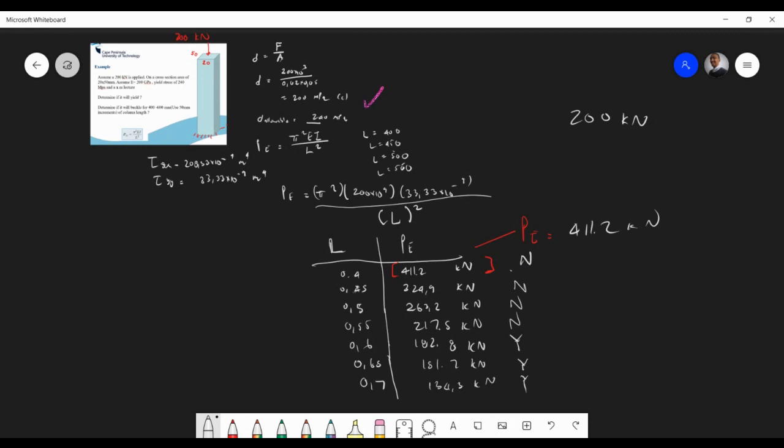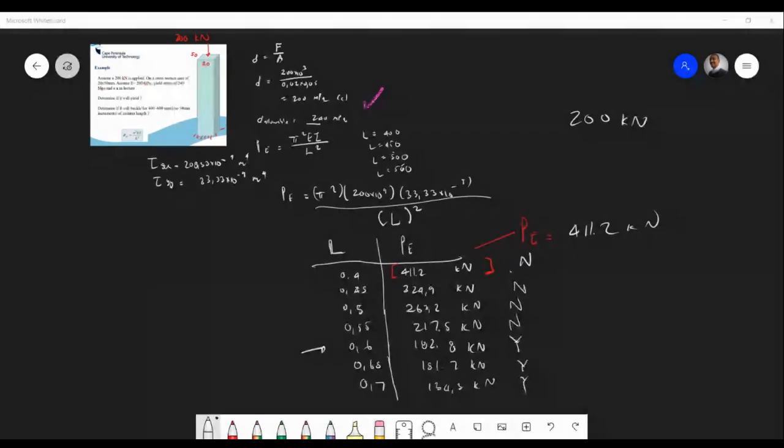You understand? But can you see what's interesting is that our allowable stress is all right, so we're still in the right realm. But look, if we make this column 600 mm, it's going to start to buckle. That's the concept, guys. It's not a state of stress. It's a measure of stability, or structural stability, if one could say that.